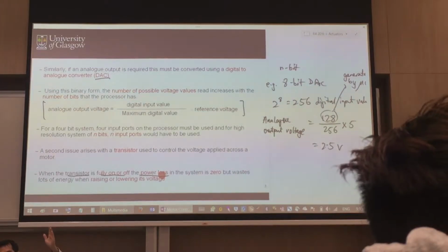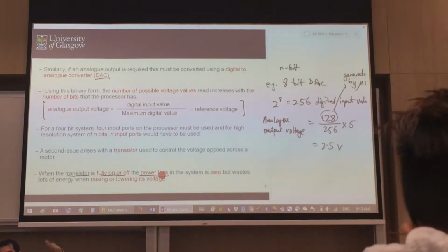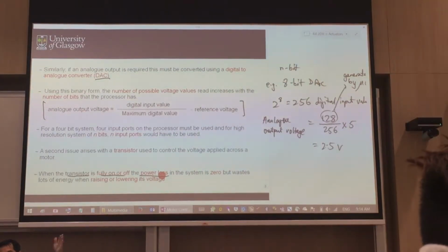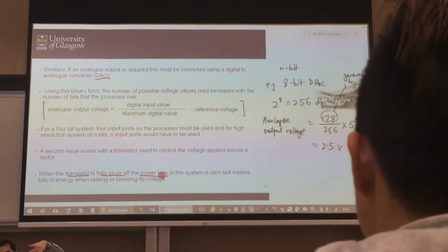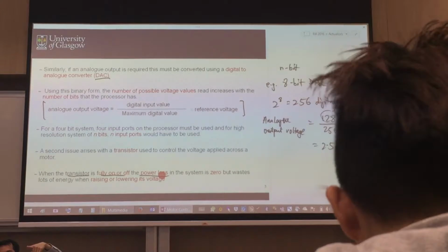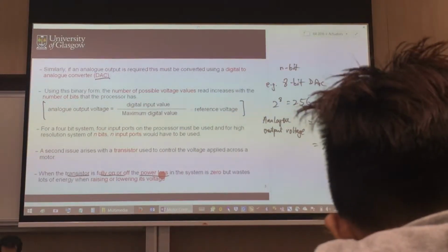So if you're using a transistor to do rapid switching, you want on-off rapid switching, because you're after that PWM signal, the on and off PWM signal. If you're after a lot of switching, your transistor will heat up tremendously under higher switching frequencies, because higher switching frequencies mean it spends more time in the process of switching. If you switch to 0 or switch to 1, then you don't have much power loss. That's the nature of your transistor.